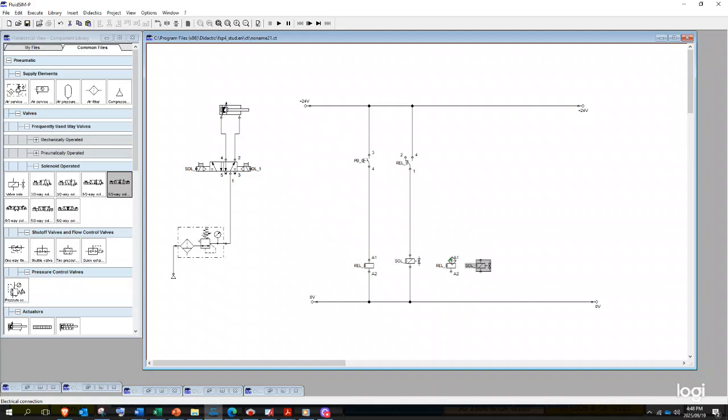And when it's direct actuation, it is connected not to your relay, but to your valve solenoid. So as long as you know that when it's indirect, my valve solenoid is connected to my changeover switch instead of my push button or sensor, it doesn't matter which side you start, as long as you follow the correct principle of your connections on FluidSIM.